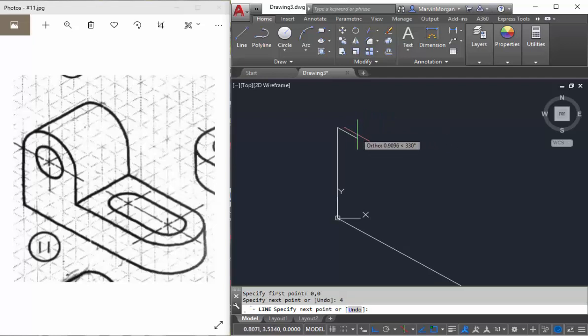At this time, I'm going to go across in this direction, and if you can kind of imagine, I'm right here at this location. I want to go across to end right here at the center point to help guide my circle. That will be a distance of 2 units based off the 2 squares you see there. So from here, I'm going to go in a downwards direction 2 units and press enter to end the command.